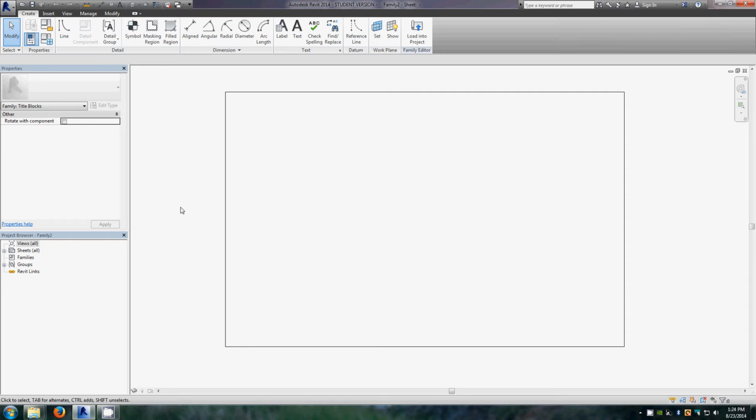First thing let's do before we get too far is save this as a drawing name. I like to do that right away so you don't forget, and when it prompts you to save, then we already have it set up. Best to save, if possible, to a folder that you've created on your hard drive, or put a folder on a desktop. If you just save to the desktop, you probably notice that it'll create a bunch of files. That's because it auto saves every so often, and so what you'll end up is a cluttered desktop. So if you don't mind that, that's fine.